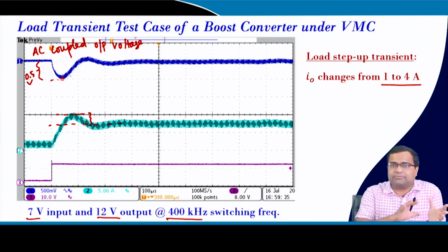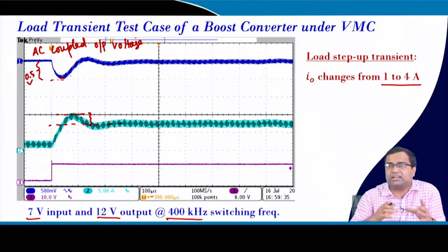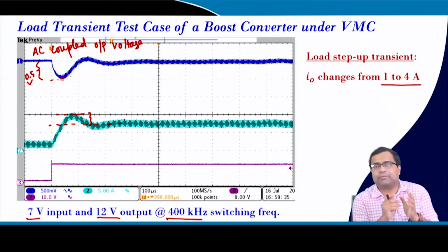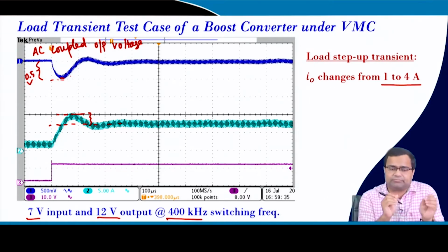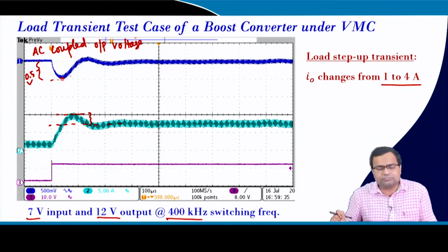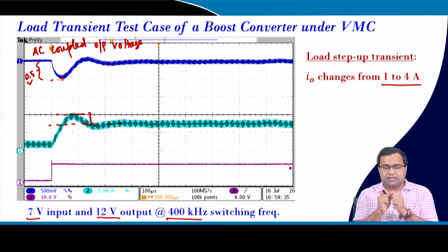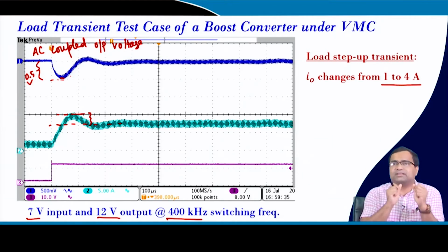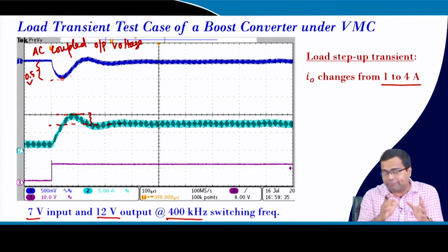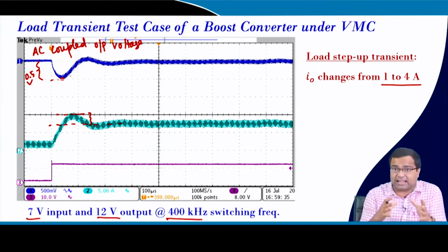Even if you take a time domain specification, you need to correlate in frequency domain, because most of the compensators are designed using frequency domain, whereas in the time domain you have difficulty because there will be multiple poles and zeros. In frequency domain we consider phase margin, bandwidth, crossover frequency and so on. So, we need to check whether the obtained performance is matching with my desired requirement or not, and often you will find they may not match, or they may match closely.